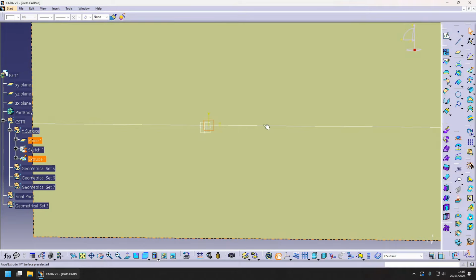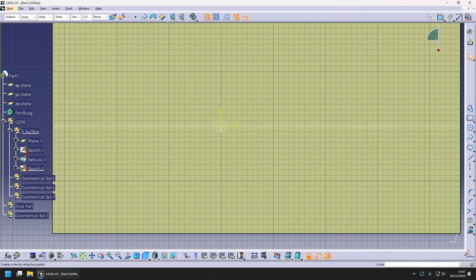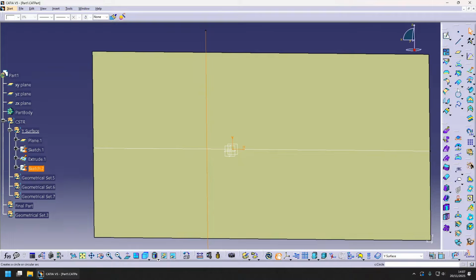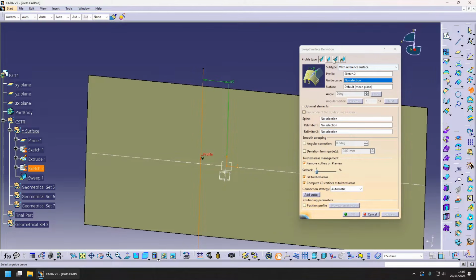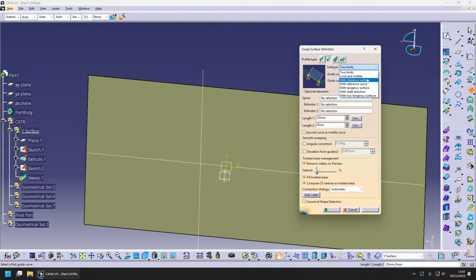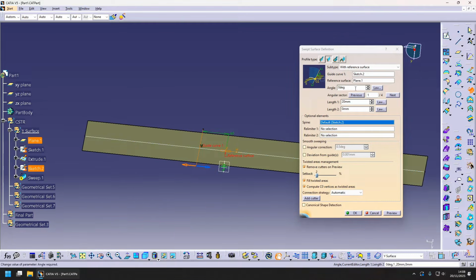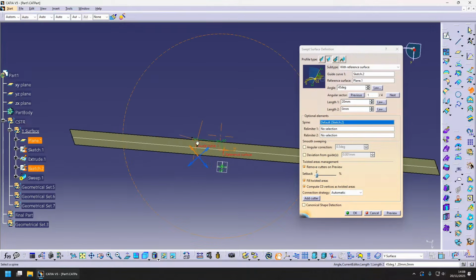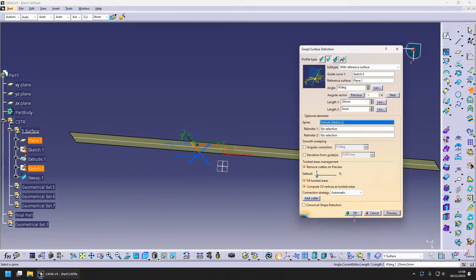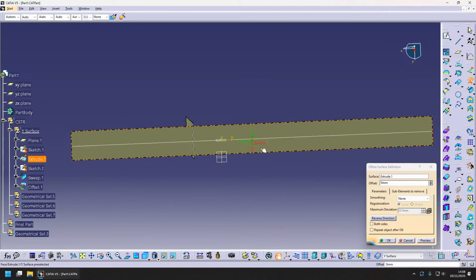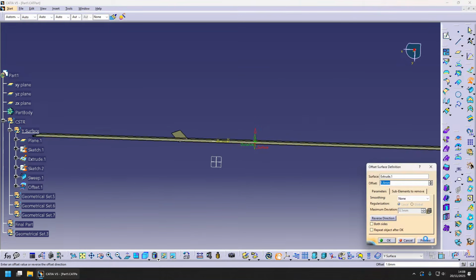Okay, this looks good. We create another sketch on this. This is so we can create the small depression here at the end. And we quickly make a line, which we fully constrain. And we're gonna use this line as a starting point for this little joggle. Then we're gonna sweep this line at a 45 degree angle with regards to the base surface. Then we're gonna offset the base surface that we did by a tiny bit, 1.6 millimeters should be enough.